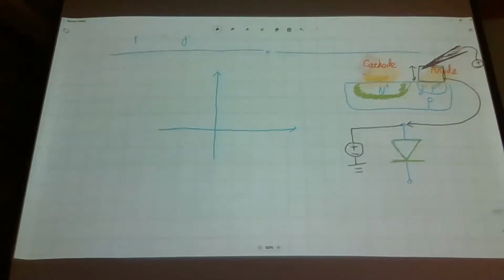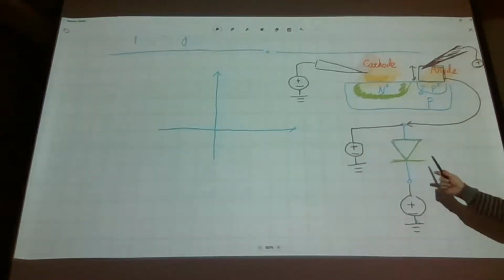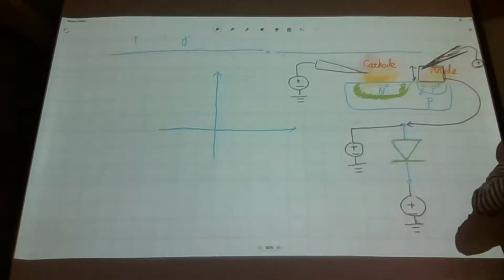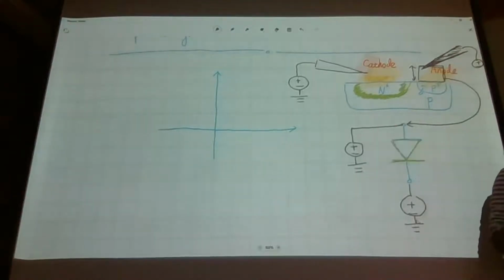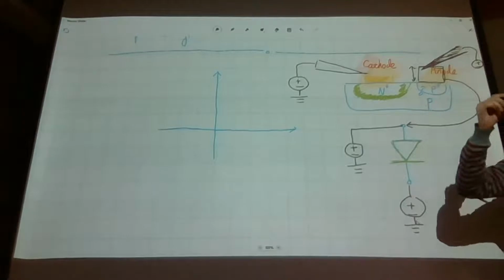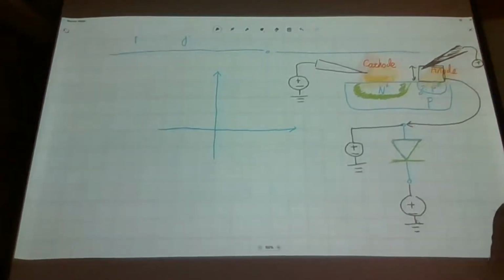And finally, of course, we have another terminal. If we want to apply a certain voltage, then we place our second metal tip, which is connected to another voltage source. That corresponds to our other voltage source, so it is in your mind when you design something using, for example, a computer program. However, to make it real in the physical world, somebody should prepare the silicon substrate, implant certain dopant ions into your system, make the metal contacts, and place metal tips on those metal contacts.